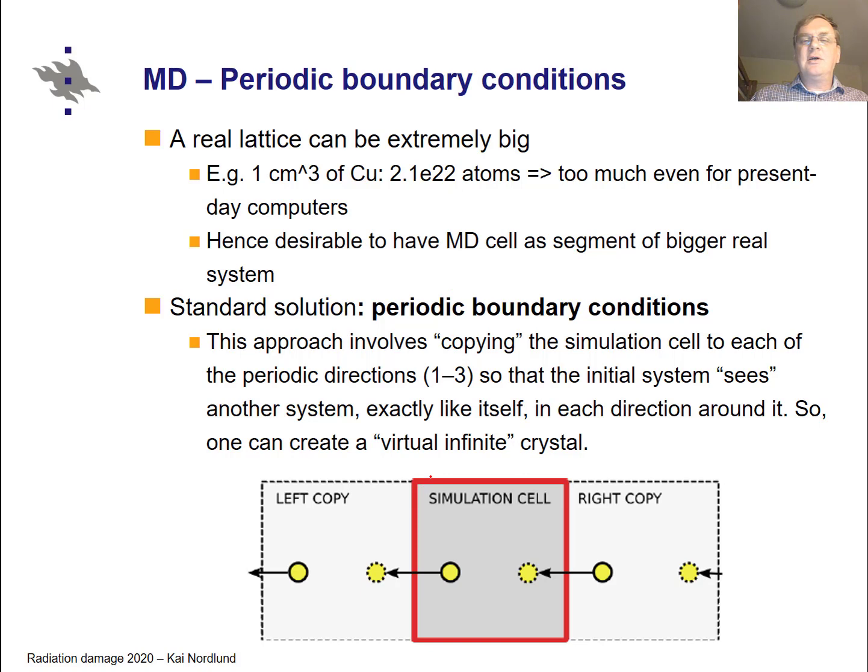But there is a smart solution to simulate these and to avoid any boundary effects. This is known as the periodic boundary conditions. This means that if an atom is at the edge of a simulation cell and it moves over the boundary, you put it back on the other side. And this is just a simple operation: this is the x coordinate, if it crosses the border, add the simulation size to the x coordinate, and then it gets here.